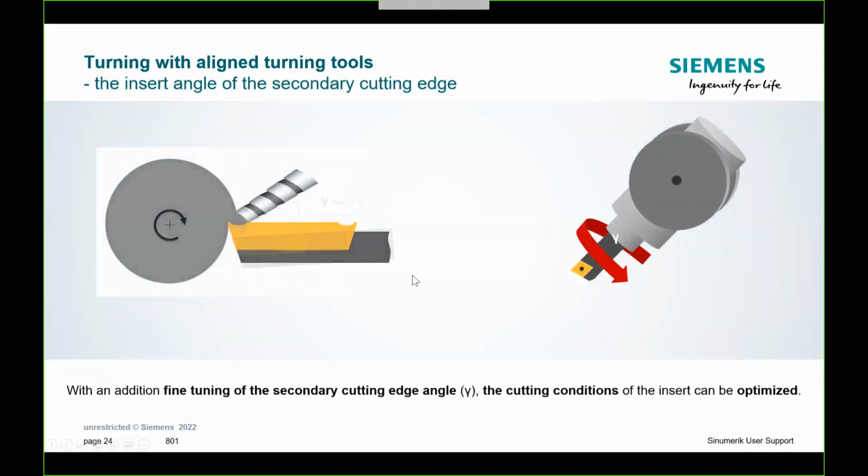Another unique little secondary thing here is we can rotate, as I said before, the gamma of the tool. So that's the tool's rotation in the spindle, not around the spindle. What that means is I can rotate it by plus or minus 5 degrees. The system limits it so you don't wind up breaking the tool or the insert.